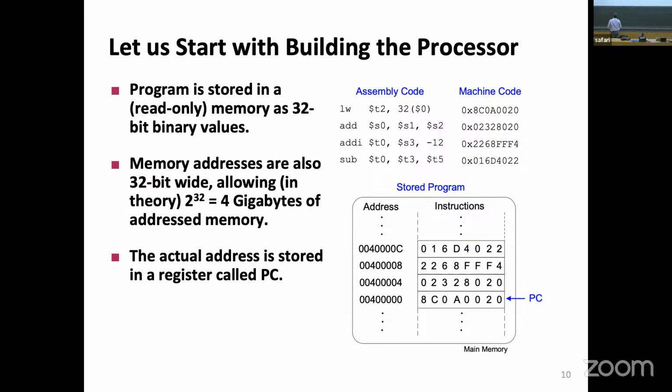So let's first start with our memory. There is somewhere in our architecture a memory. This memory is clocked for writing, but it is actually combinational for reading. What happens here is we have an address, and this address can be 32 bits wide, tells us which data to read out. Now, an instruction memory, this guy, we will not be writing into this instruction memory. We will only be reading from it.